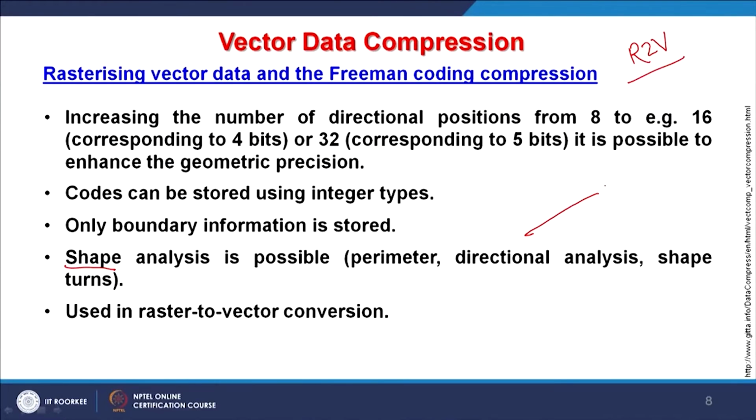So, if there is a contour and a value 100 is written here, and I have trained this one, it will keep digitizing until it stops here, because here it is confused. Then I have to say just ignore whatever is written and restart from here, and it will reach this end. Therefore, there is no fully automatic raster to vector conversion technology, nor any software available.